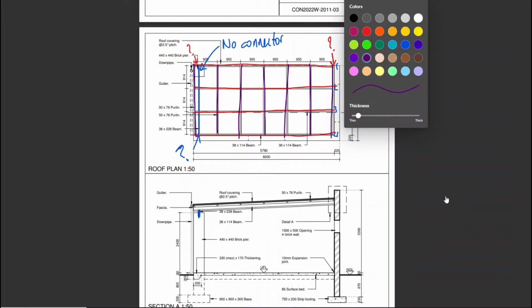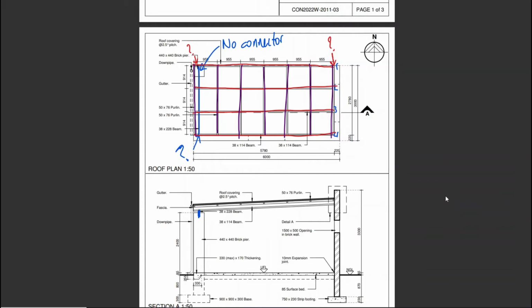Now, your purlins are fixed to your secondary beams. And how are they fixed to your secondary beams? We're going to take a look. Let's use that one as an example. So, for our first question mark, main beam to brickwork. Okay, that is an Eco 38L. It's actually a truss hanger, right? Okay, on that side.